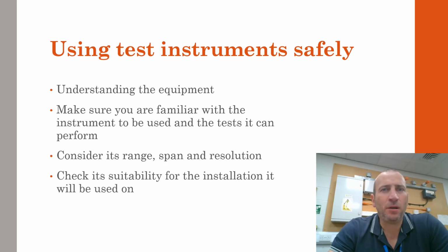Is the installation a low voltage, that is anything between 50 and 1000 volts AC or 120 volts and 1500 volts DC? Or is it extra low voltage, that is anything less than 50 volts AC or 120 volts DC?